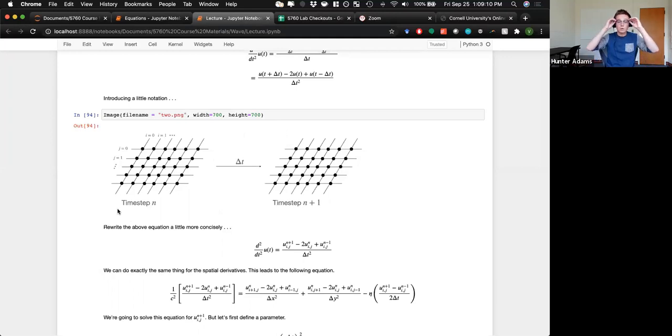Right, so you think about one state machine that walks through serially as many nodes as you can in 1,000 or so cycles, and then you take that logic and you copy it over and over and over again as many times as you can until you run out of hardware. And the hardware that you're going to run out of might be multipliers, it might be logic elements, it might be memory, it depends on your specific implementation. But you're going to fill the FPGA with as many of these things as you can.